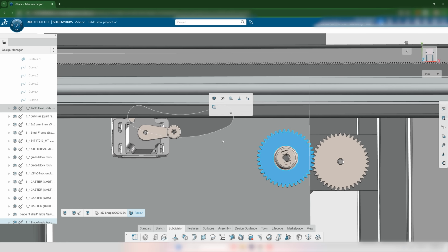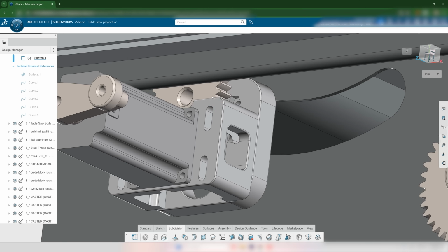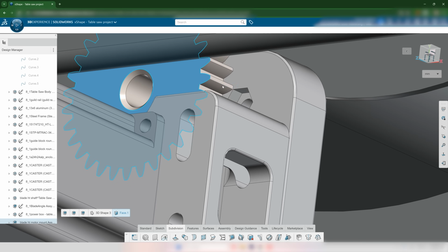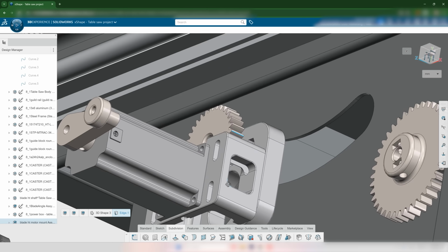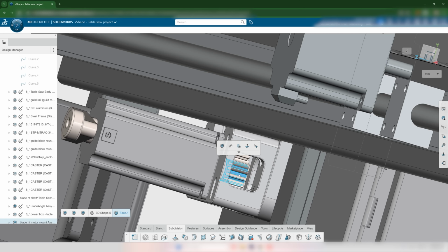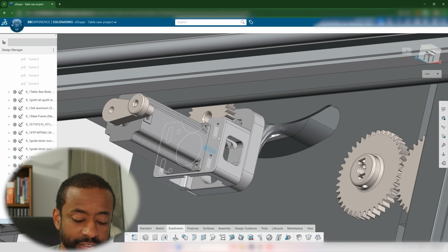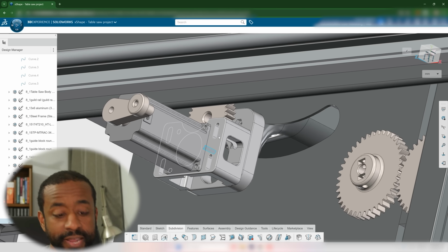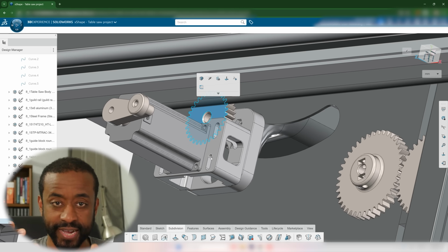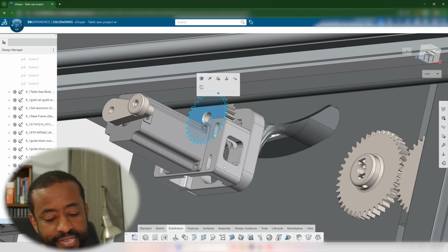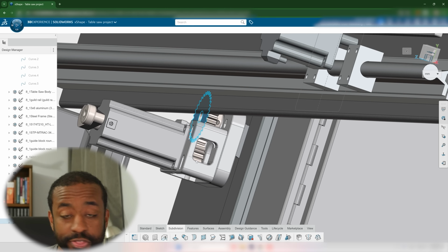And similarly here, the force needed to lift the blade up and down wasn't very much at all. And so these are 3D printed gears, but they're relatively thick, as you can see. And I think there's a 2-to-1 or 3-to-1 gear ratio. You can see the smaller gear right there. And this whole mechanism was actually pretty interesting to design. These slots allow me to slide this mechanism up and down to adjust the fit between this gear and the other gear. It lets me tighten the set screw in there. I can change that bottom gear if I want. So quite a lot of thought went into making these 3 pieces, but they're all 3D printed pieces.